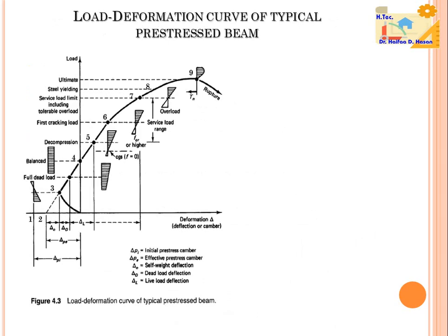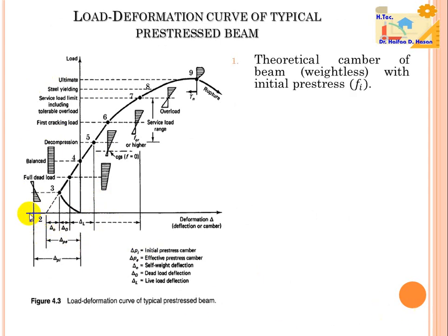Load deformation curve of a typical pre-stressed beam. Here we can see in this figure the load deflection curve of a typical pre-stressed beam from the beginning of making the pre-stress section. In point 1, we can see the theoretical camber of the beam weightless with initial pre-stress, and also we can see delta pi equal to the initial pre-stress camber.